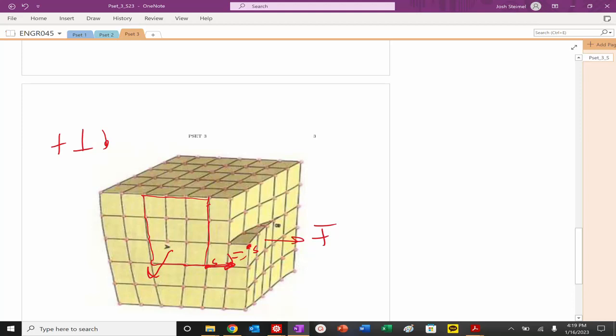So I'm going to start here. So I've gone 1, 2, 3 steps, but I'm going to go 1, 2, 3, 4, 1, 2, 3, 4, 1, 2, 3, 4, and then I still need one more step here. So this is my start. This is my finish. Start to finish. Anti-parallel to Burgers vector. That's a left-hand screw, and that's it.